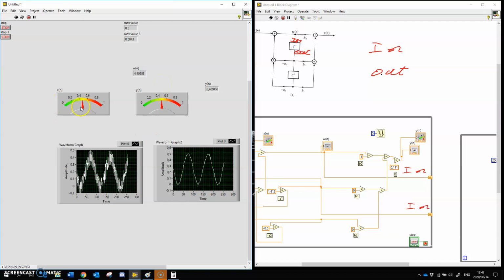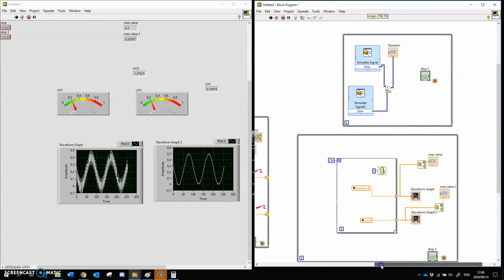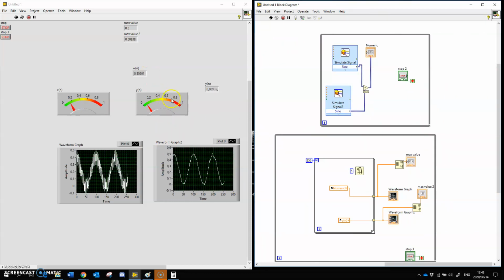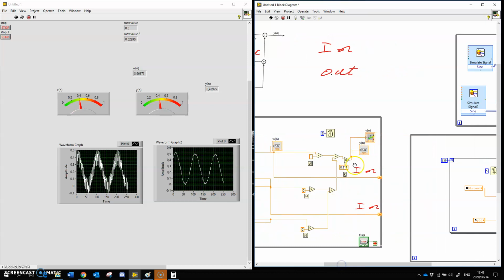We can now see there's our noisy needle, there's our smoother needle, so it's a better control circuit measuring. We're still not at 0.4, we can still calibrate it to 0.4, adjusting that value until we get 40 degrees Celsius, as I said in the beginning. But this is just a nice indication at the moment. So the calibration would be done depending on what the gain is of your preamplifier, depending on what your sensor is, but that would be that.